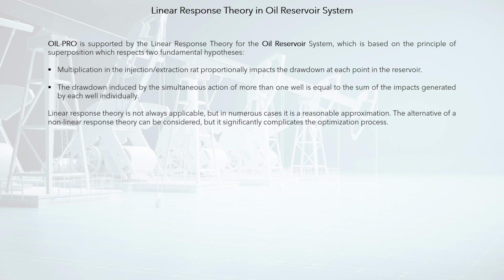Multiplication in the injection or extraction rate proportionally impacts the drawdown at each point in the reservoir, and the result, drawdown, induced by the simultaneous action of more than one well, is equal to the sum of the impacts generated by each well individually. Linear response theory is not always applicable, but in numerous cases it is a reasonable approximation. The alternative of a nonlinear response theory can be considered, but it significantly complicates the optimization process.